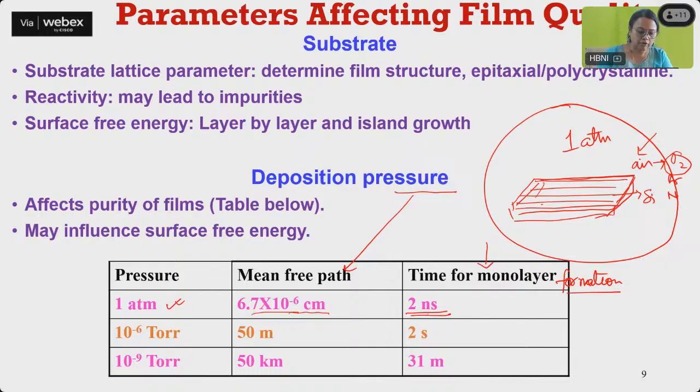Now if we go to 10⁻⁶ torr, which we generally get by using a combination of a rotary and a diffusion pump, the mean free path increases to 50 meter. 50 meter is the distance one atom will travel inside this kind of vacuum before it encounters another atom and gets collided. And the time for monolayer formation because of the environmental gases is 2 seconds.